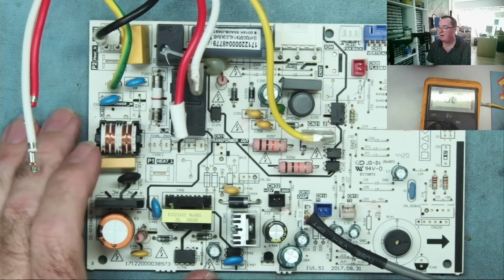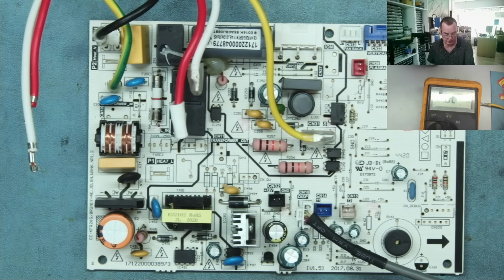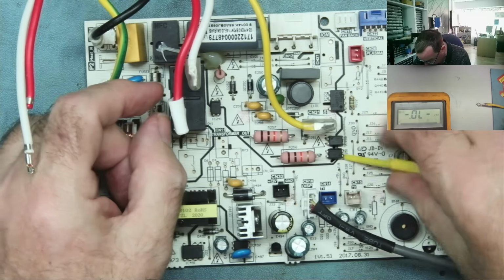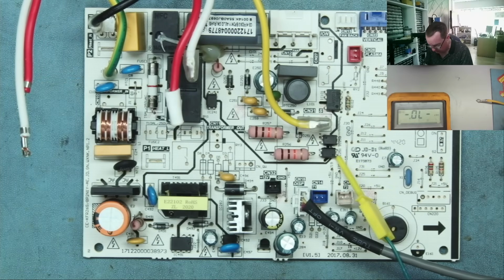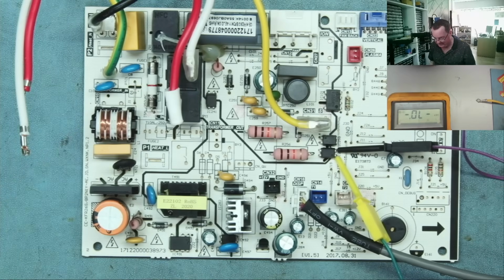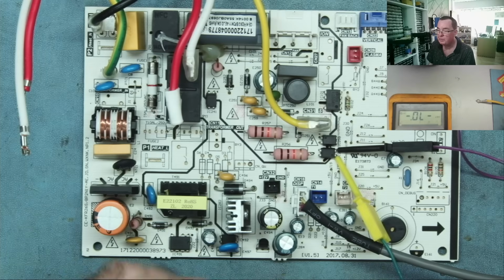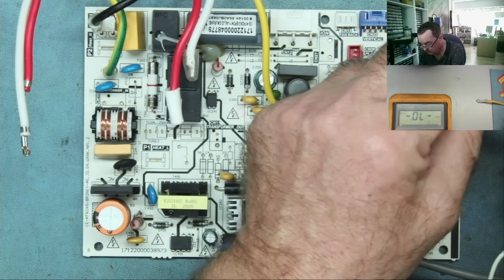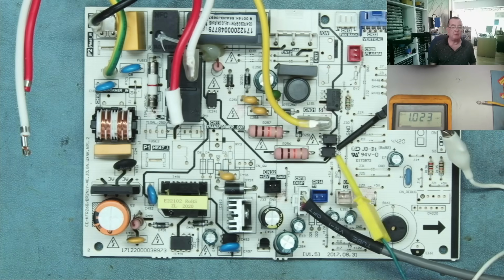Let's check these optoisolators to see if they actually function. There are a few ways you can do this. I find this probably about the easiest. So clip a couple of these little clips onto the optoisolator, on the LED end I'm using. Could do it the other way, depends how you feel. Okay. Put the meter into diode mode. So this should be the positive end of the optoisolator where the dot is. Positive end of the LED in the optoisolator, I should say. Okay. Just clip the wires on. Yeah. Just over 1 volt, what you'd expect.